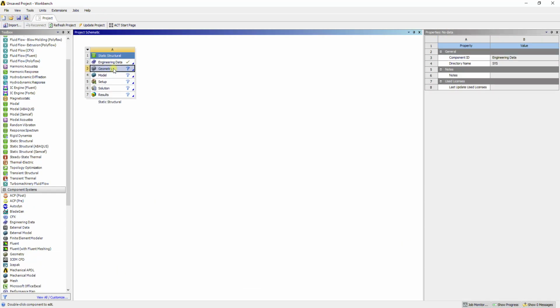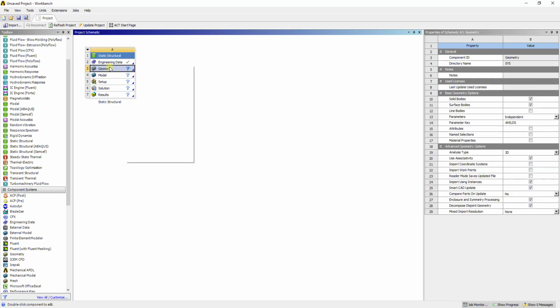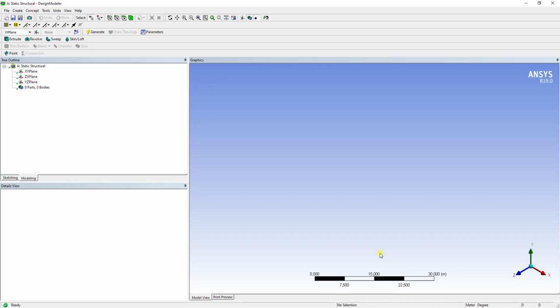Today we are going to use just static structural to find the ultimate buckling load. We cannot find the critical buckling load with this method, but it is very fast compared to the other method. If you want to find just the ultimate buckling load, you can use that. When we are doing sketching, please sketch the same as me, because I will define a lot of parameters, a lot of dimensions, so you can get confused. That's why please sketch the same as me.